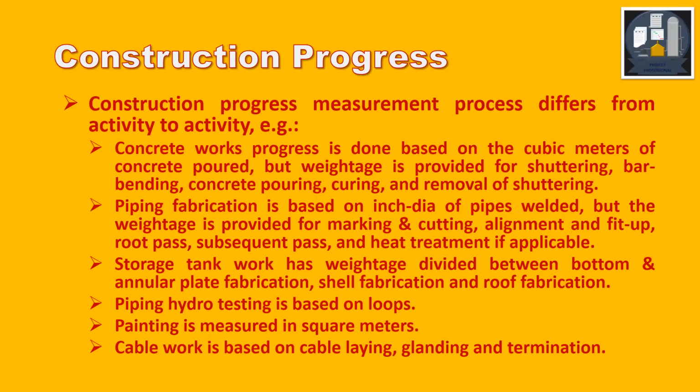Then pipe fabrication is based on inch-dia of pipe fillet, but the weight is provided for marking and cutting, alignment and fit up, root pass, subsequent pass, heat treatment if applicable.